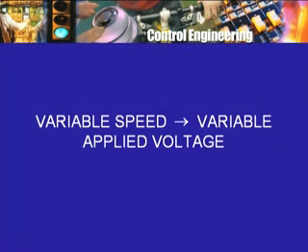Then the same expression can be used, and you will see that if you apply the same armature voltage, then the speed of course is going to be close to 1500 rpm. So in order to make the motor run at a lower speed, we will have to change EA not by a small amount but by a considerable amount. If you look at the electrical equation, the back EMF is nearly equal to the applied voltage if the armature drop is small, which it is, and so roughly for a given motor the applied voltage will be proportional to the speed. So if for 1500 rpm you had 230 volts DC, to get 500 rpm, 1/3 of the speed, the applied voltage will have to be closer to 1/3 of 230 volts. So in other words, there has to be a large change in the applied voltage.